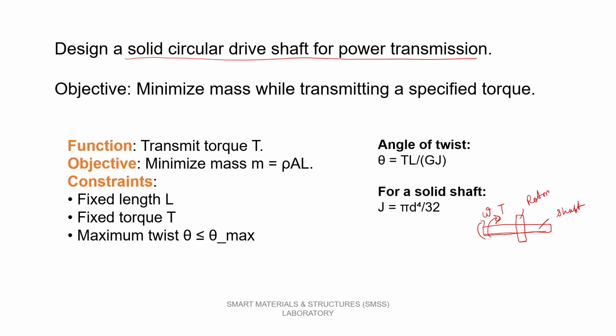This shaft is of course not in the free state, but there will be some bearing to take care of the supporting forces to vertically sustain it. But these are just bearings, so it just takes the vertical load; it does not restrict the movement of the shaft. Okay. If it restricts, then it will become a structure.